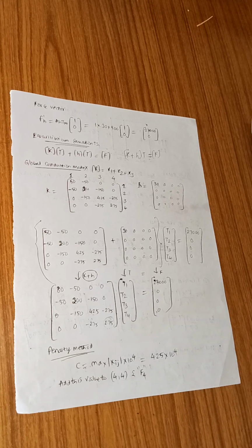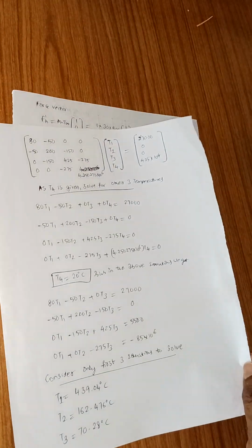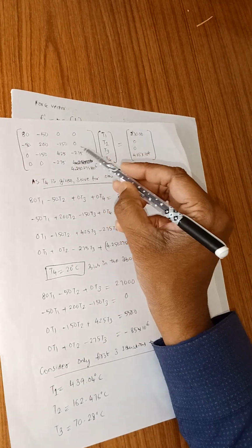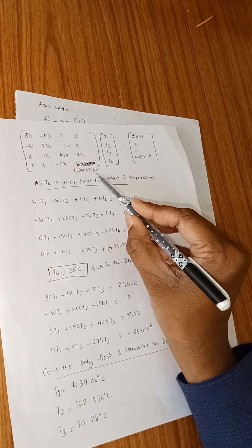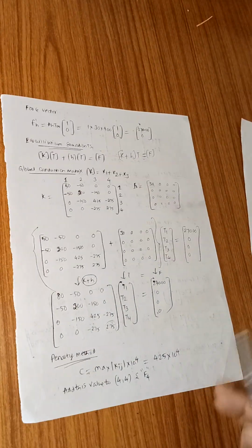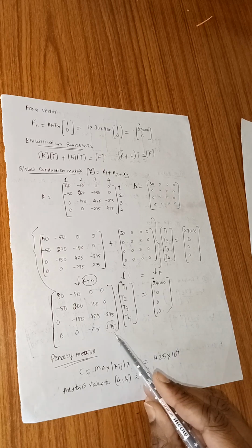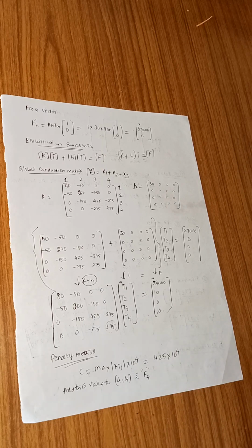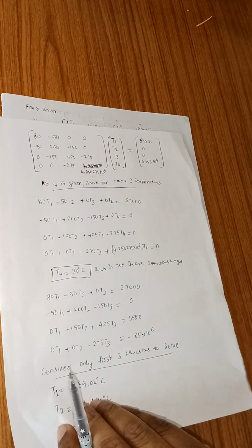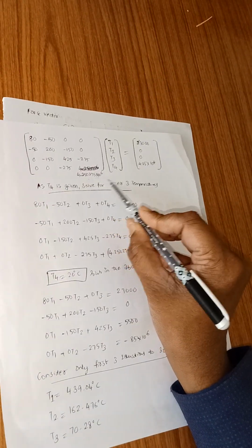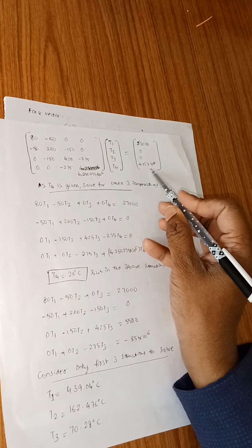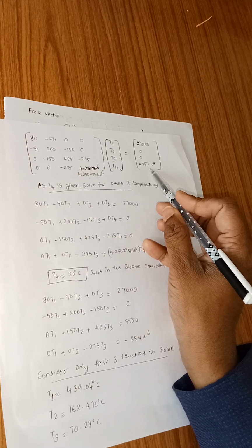So I've just done the change over here. You can just see in this page. So this is the K plus H matrix. Here in 4 cross 4, I'm going to add that 425 into 10 power 4. Already the element that was present there was 275. So 425 into 10 power 4 plus 275. When you're adding it, you're going to get something like 4.250275 into 10 power 6. Then, here it was 0, so 0 plus this is going to be the same.